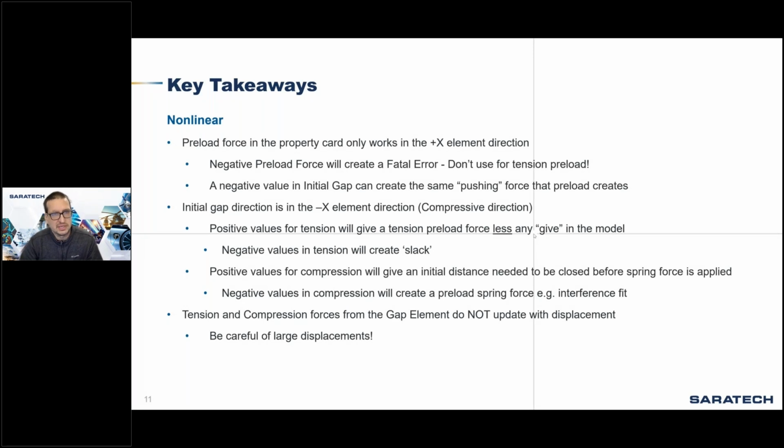So preload force in the property card, keep in mind that works only in the positive X element direction. If you try to use a negative preload force, it'll give you a fatal error, so I don't recommend that. A negative value in the initial gap can create that same sort of pushing force that preload creates. Or in our case, sorry, that should have been a positive value. Initial gap direction is in the negative X element direction, so compressive.